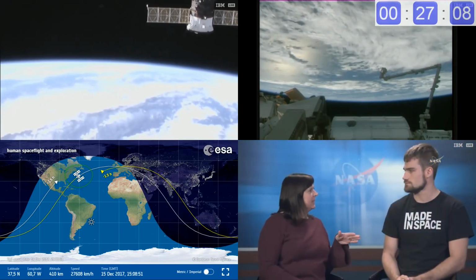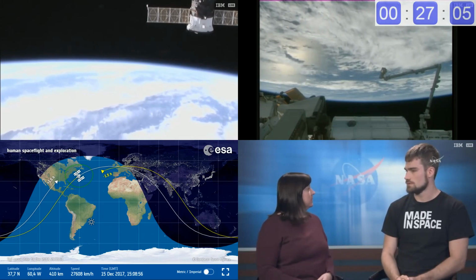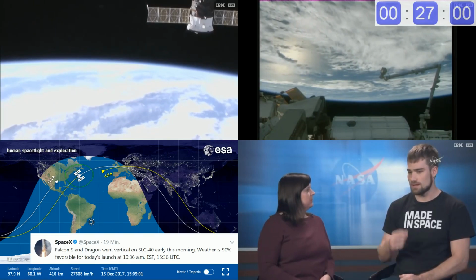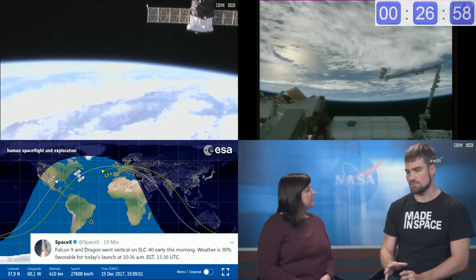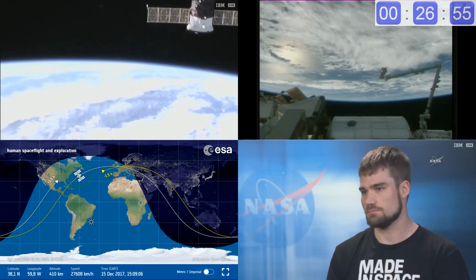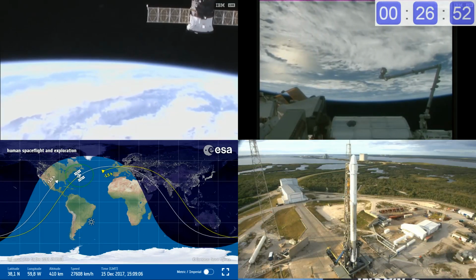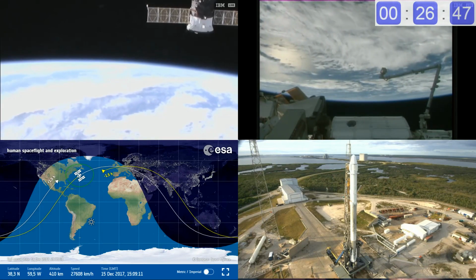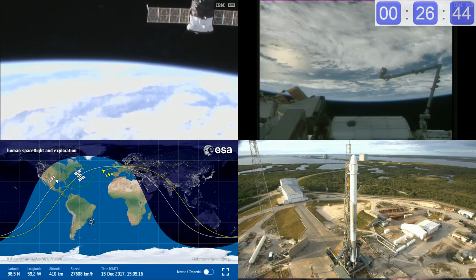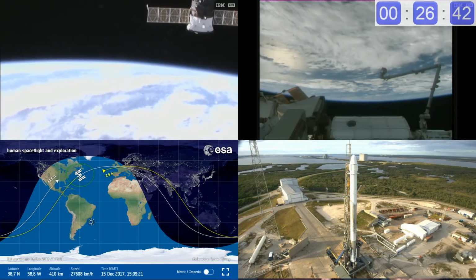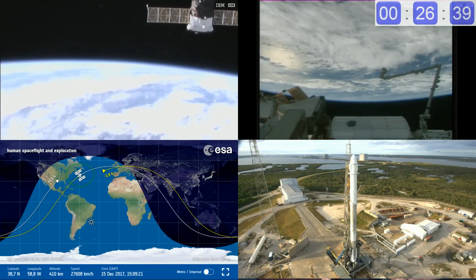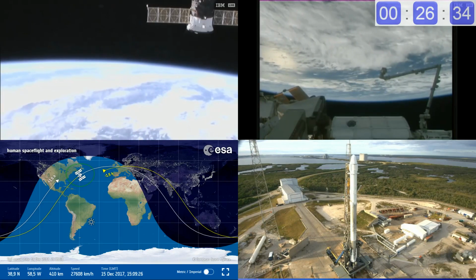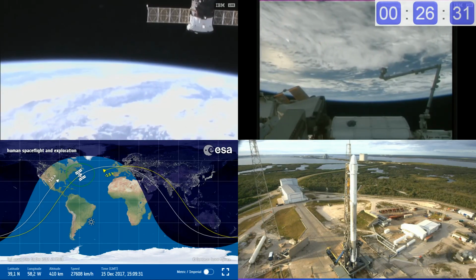So what exactly is Z-blan and how is that different from what's currently being used in fiber optic cables? Current fiber optic cables are in general made of silica. Z-blan is a special material made of a whole bunch of different elements that is just more stable, the theory goes, in 0G. Okay, so you say it's more stable in 0G, and then you're going to bring that down to Earth. What do you hope to happen when you implement it here on Earth? Well, when we get it down to Earth, we'll take it for study, and we're hoping to see that the attenuation is a lot less than silica fibers. The attenuation is how much light is lost when you shine a light through the fiber optic cable.